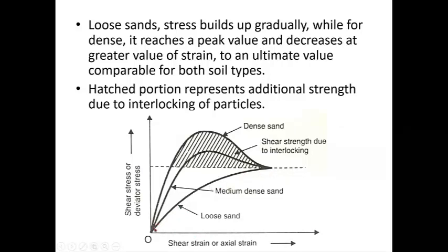Now correlate it with the soil slowly rolling over each other and attaining a dense state and attaining its maximum shear strength, as you can see here. Correct? Can you see that? It slowly started coming into a dense configuration, and once it has come to its best possible configuration, here you can see that it has reached its peak.